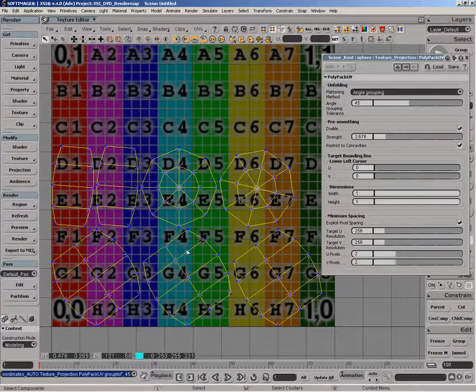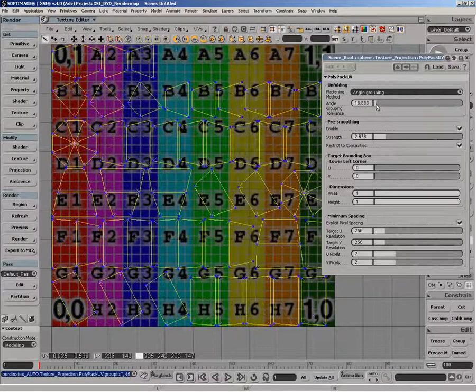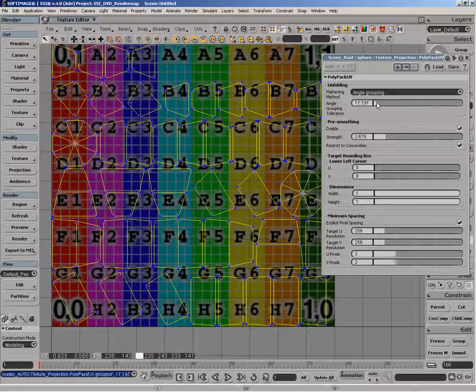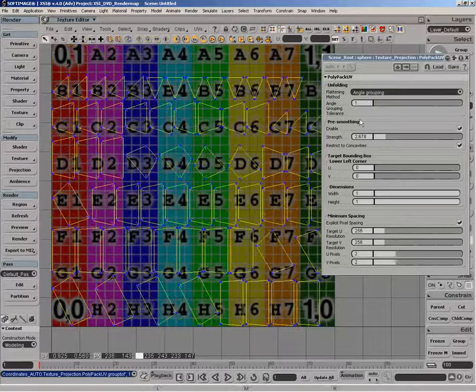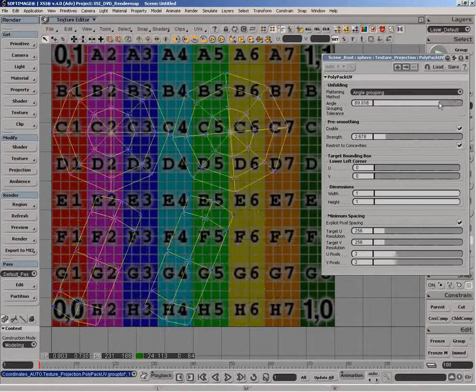And you can see we get a fairly visually coherent UV sampling. As I decrease the tolerance, so we've got a much more minute threshold for the angle, all the polygons start breaking apart and creating their own separate islands. If I went with a tolerance of 1, so polygons within 1 degree would be grouped together, you can see we're pretty much back to our unique UV layout. And as we increase it, you can see we get larger islands.